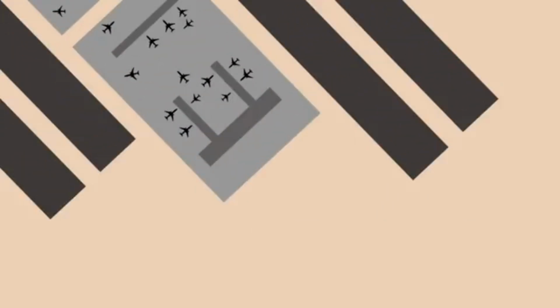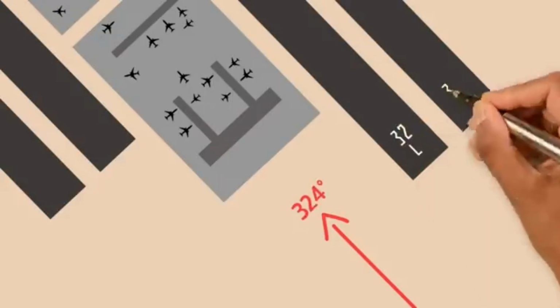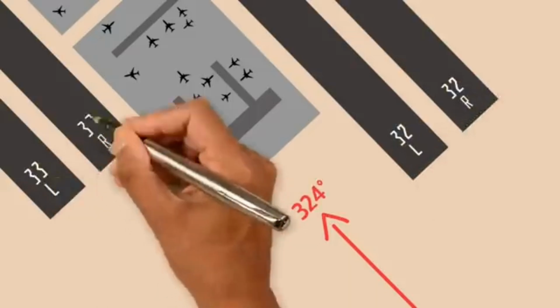If the runway is located at 0-90 degrees, airports that follow the FAA rule erase the leading zeros and use only the number 9. But many other airports also mark it as 09. If there are 2 parallel runways, they are identified by adding the letter of left and right below the runway number. If there are 3 parallel runways, the letter of center is added. In an airport with 4 parallel runways, the 2 runways are numbered differently to avoid confusion. For example, if the magnetic north of these 4 runways is 324 degrees, the runway number is determined like this.